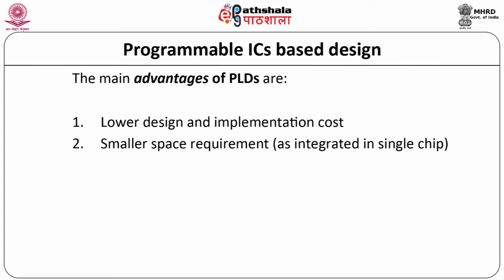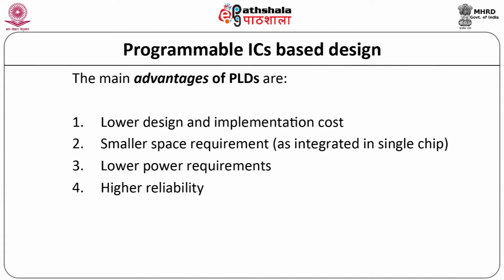Hence, we have another advantage, that is smaller space requirement. Due to the single chip solution, the power requirements are low. Hence, PLD provides the option and advantage of lower power design. As there are minimum interconnections on the board, the reliability of the design is high.